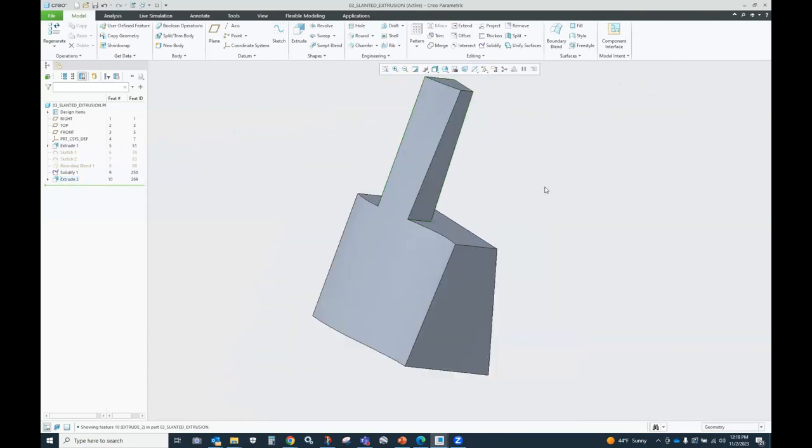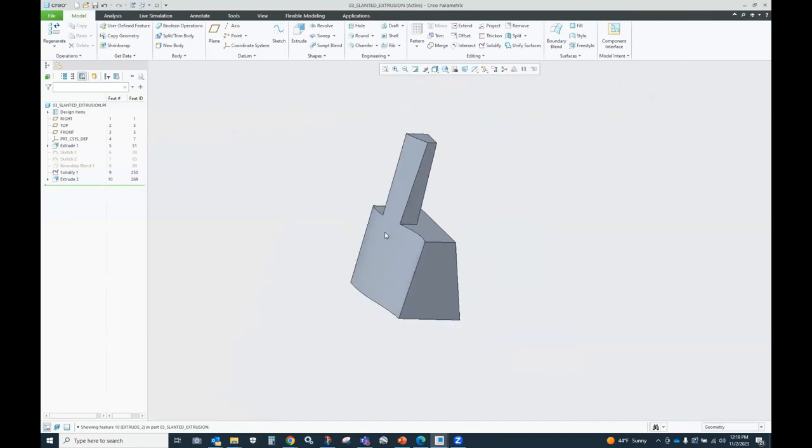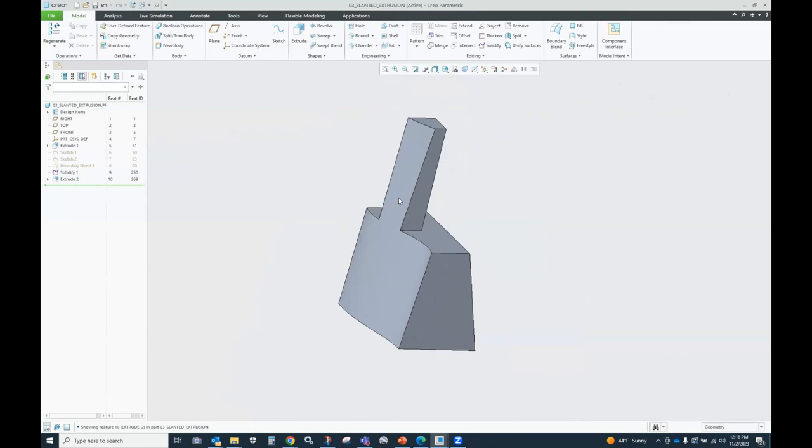So, don't be afraid to try things like that. If you work on consumer type products where you have more organic kind of geometry than anything else, try using those open cross sections. When in doubt, make it closed, right? When in doubt, make it closed. But if you can get away with fewer features to get where you want, you're always better off, right? Fewer features, fewer IDs, fewer references, more robust, right? Is it that Papa John's slogan? Better ingredients, better pizza, right?